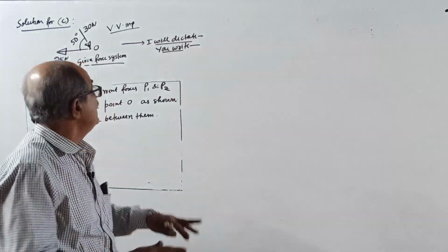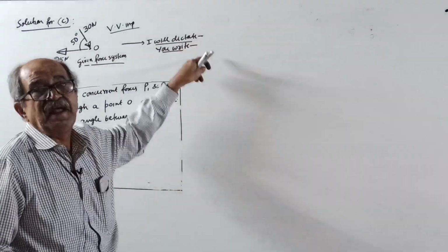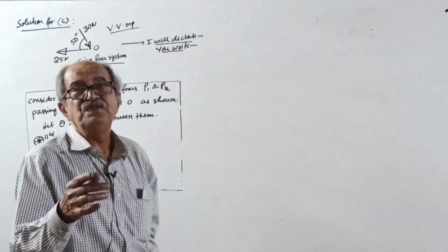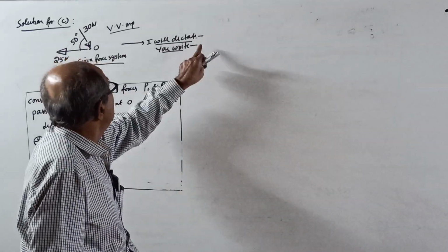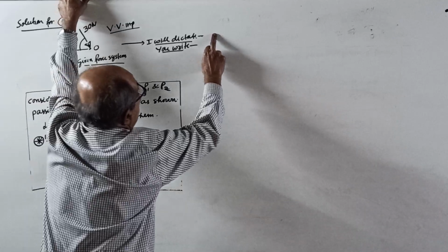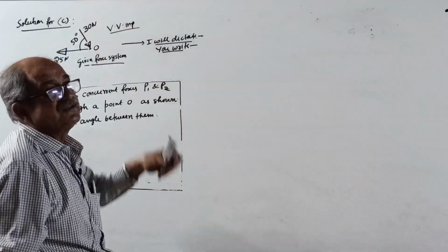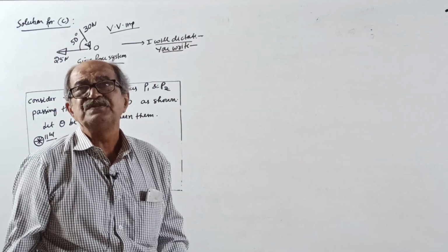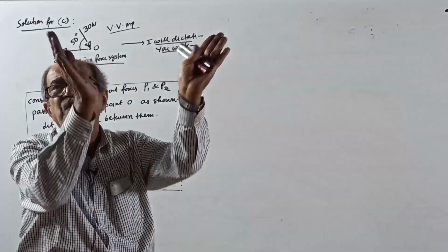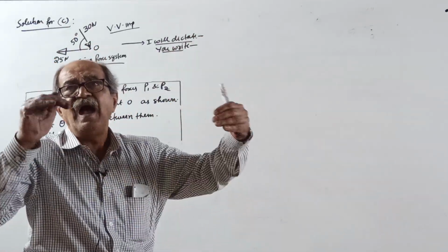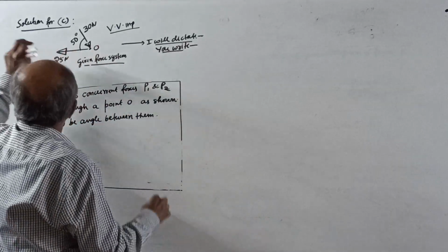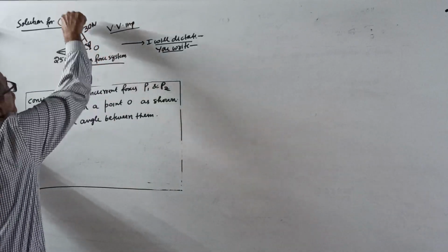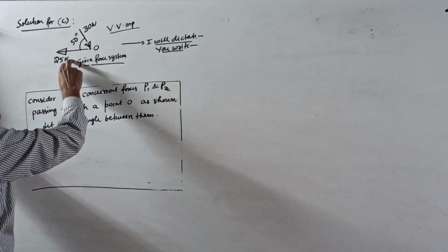Write this note first, then I will dictate technical terms. I will dictate, you write. When we apply the law of parallelogram of forces, it is required that both forces are either acting away from the point or acting towards the point. But here, 25 Newton is acting away from the point O, and 30 Newton is acting towards the point O. Therefore, we have to make a modification.